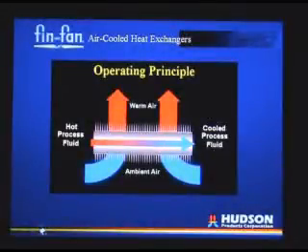Basically, the principle of an air-cooled exchanger is to pull in ambient air and blow it across a finned coil and pick up heat and reject that warm air to the ambient. Obviously, the performance of the cooler is driven by your ambient air temperature. The higher the temperature, the lower your driving force between the process fluid and the air, so your available heat transfer is restricted.